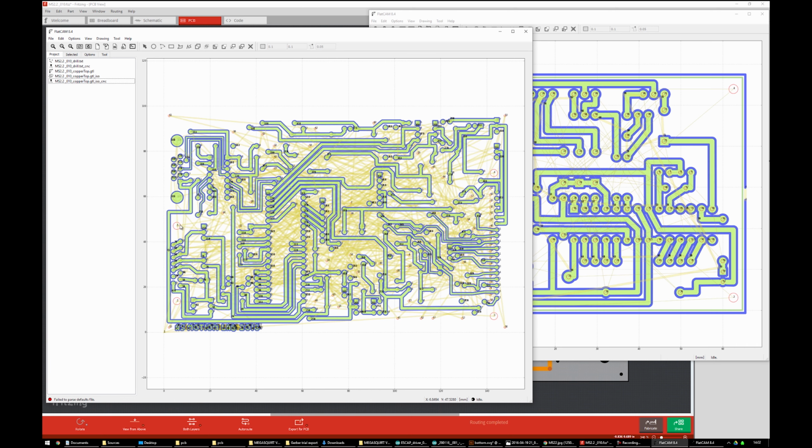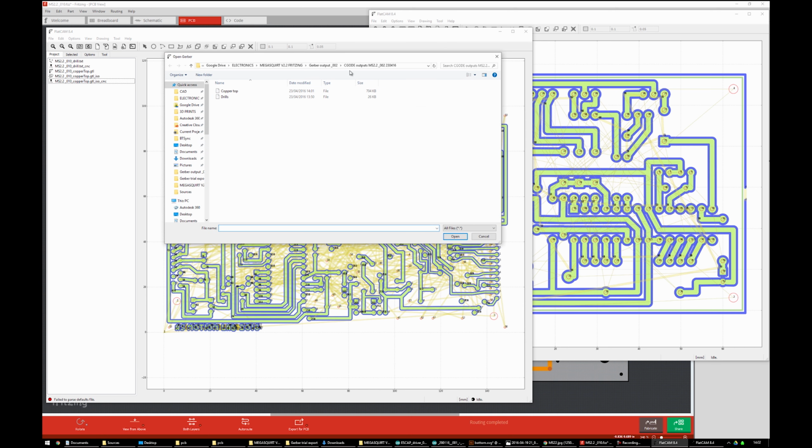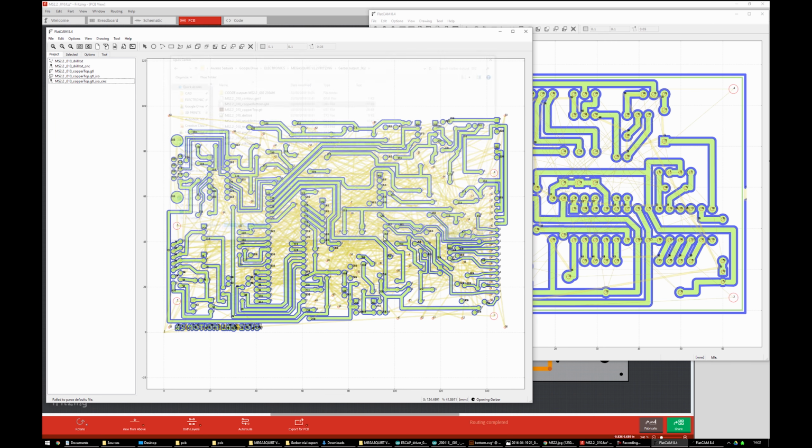Generally, the fixing is either plastic or is grounded anyway, so the fact that it's just going to be a hole is fine. We don't really need an island, an isolated circle around it. Anyway, so let's load in the copper bottom. Open Gerber, copper bottom, GBL. You can see from the file size that it's quite a lot less detailed than the copper top.